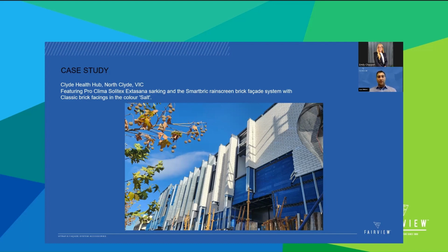I think this one was also a question about thermal bridges, about G2 aluminum. Usually the thermal bridges, whatever your cladding is, are located in the contact between your subframe and the back wall, or for example, the fixings penetrating the back wall. So whatever the system, either G2 or Stream, it's important to minimize the point of contact or the area of contact between the aluminum subframe and the back wall. So thermal breakers are the right answer for that. You're welcome, Robert.